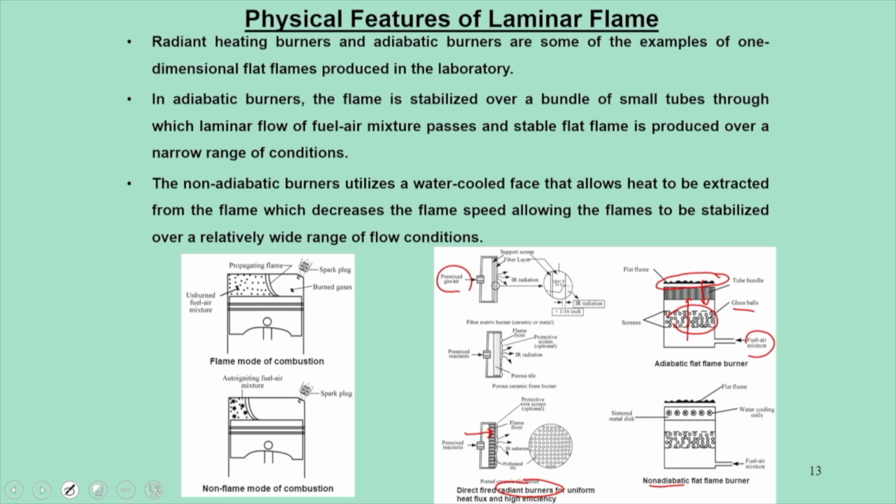So there are two possibilities. The flame can sit on the surface, that is the most ideal case. The flame may blow up. Blow up means it has too much momentum. It doesn't sit on the surface, rather at some distance from the surface. The other situation is that the flame can propagate back.